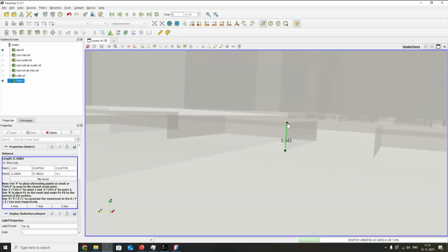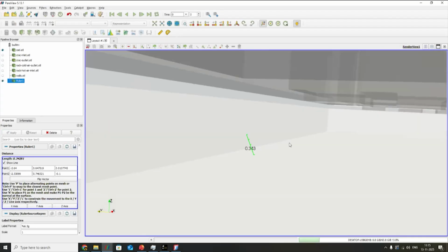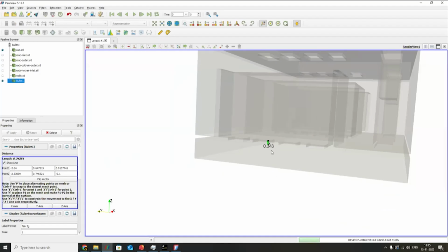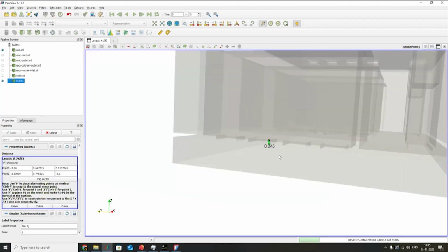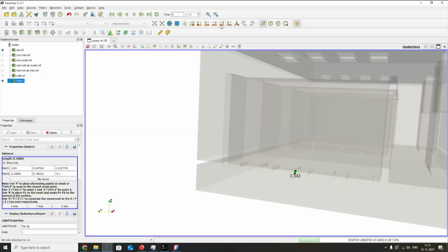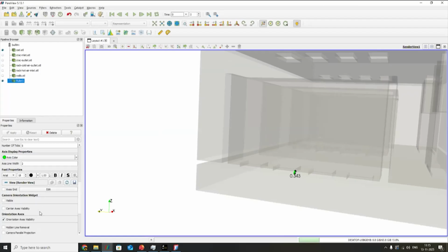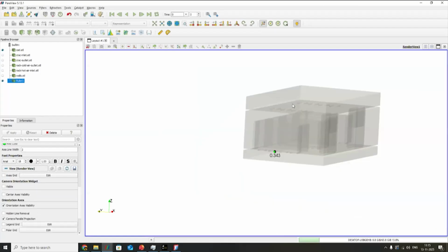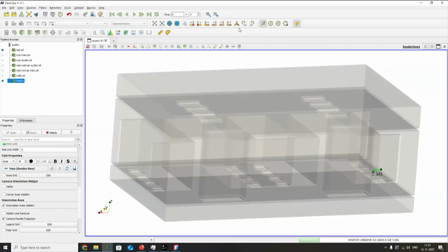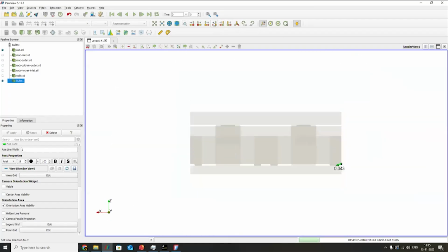Click on apply, and it will show you the height, but it is not showing it accurately right now because I did not click using the normal view. It is something else only. So for that, you need to measure it in a normal view. You can go to camera parallel projection. You can set the view, and you can see it was measuring something else entirely.